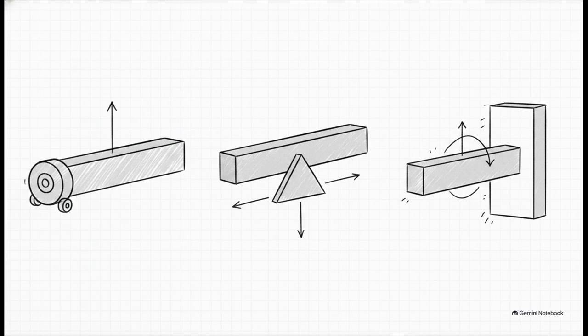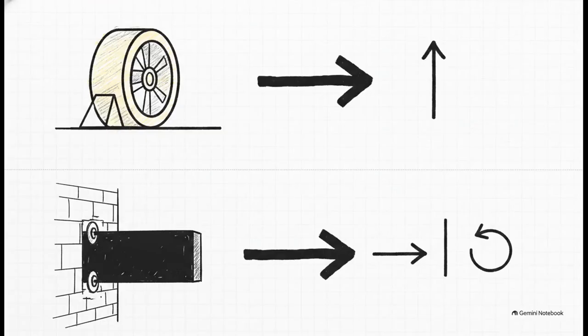This could be single known forces, like you'd see with a roller support, or unknown multi-directional forces, like a rough surface or a pin, or even couples from a fixed support. In modern industrial maintenance, getting this right determines whether you prescribe the correct replacement bolt or risk a joint completely failing. For exam time, remember that correctly identifying your support type is the absolute key to applying your equilibrium equations.